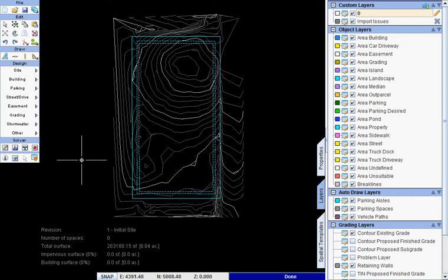This is a brief demonstration of site optimizing software that we're using at Haeger Engineering. Site optimizing software is a new technology in the civil engineering field that allows for automated site planning, grading, and cost estimating to be done in a CAD environment at a very early stage of a project, suitable for site evaluation. If you're familiar with BIM in the architectural field, this site optimizing software shares a lot of the same functionality.